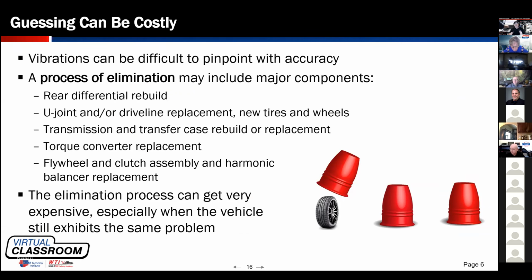I mean, gosh, you'd drive a car and you'd feel a vibration, and you'd grab the guy that's been doing it for a couple decades longer than you. He'd drive and go, "Oh, that's a bad U joint. Oh, that's a flag pulling drive line. You've got a tire that's out of balance. You've got a rear end bearing going out."